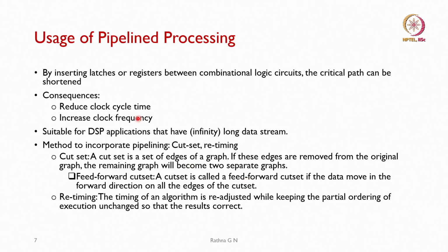So, coming to the usage of pipeline processing, how can we do it? We can do it by inserting latches or registers between combinational logic circuits. That way we will be reducing the critical path, or it can be shortened.